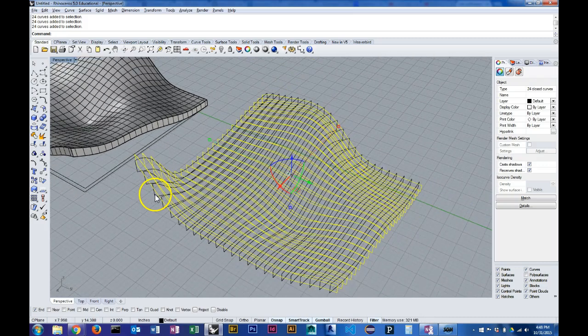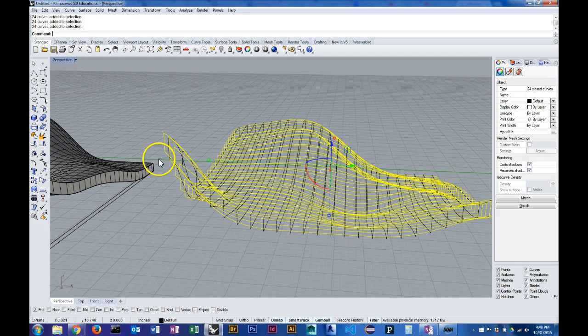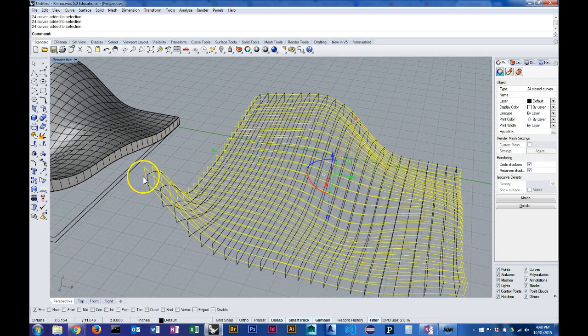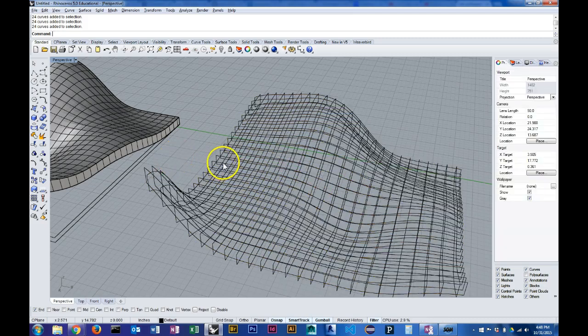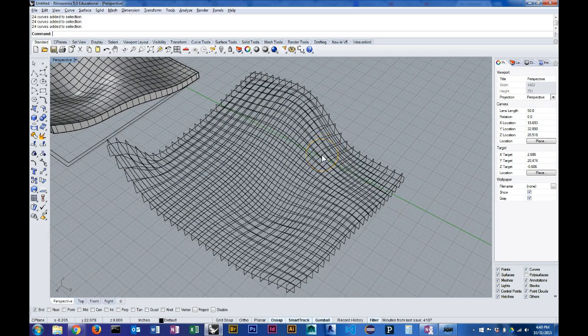Okay, so just some assumptions at the outset. The first one is that these ribs are half an inch tall, and so the notches that we'll need to make in them will need to be half of that, so a quarter of an inch. So the top layer will be notched on the bottom, and the bottom layer will be notched on the top. And the other assumption that I'm making is that the materials that we're going to use to laser cut are 1/16 of an inch thick. So a museum board or mat board or something of that nature.